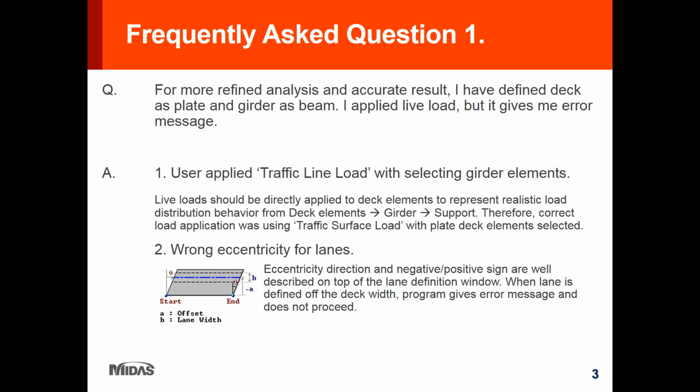Additionally, as you will notice in the program, traffic surface lanes do not have load distribution options, because for the surface lanes, deck elements are directly selected for the lane application, while line lanes are based on the girder elements.